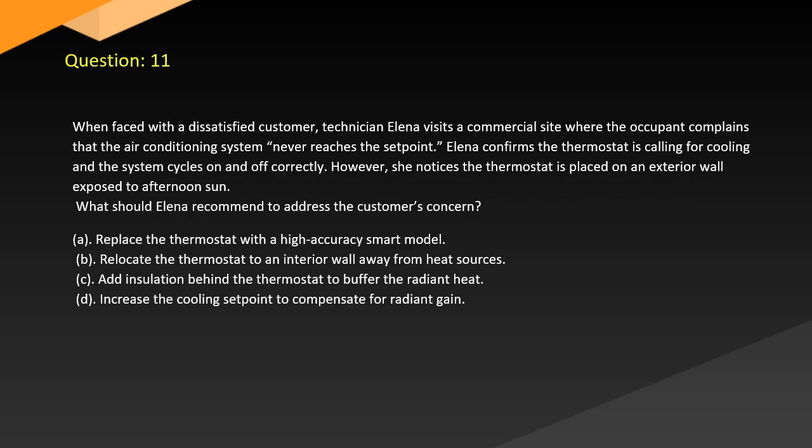Question 11. When faced with a dissatisfied customer, technician Alina visits a commercial site where the occupant complains that the air conditioning system never reaches the set point. Alina confirms the thermostat is calling for cooling and the system cycles on and off correctly. However, she notices the thermostat is placed on an exterior wall exposed to afternoon sun. What should Alina recommend to address the customer's concern?